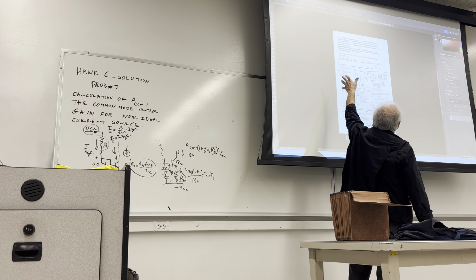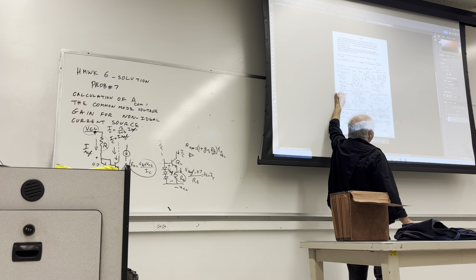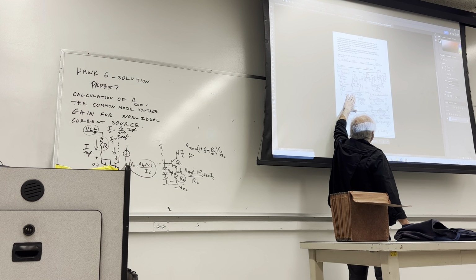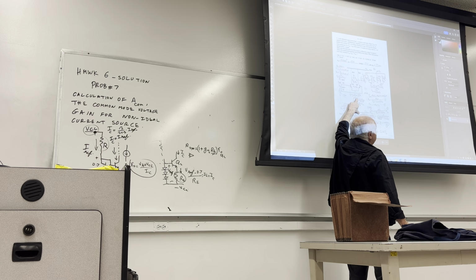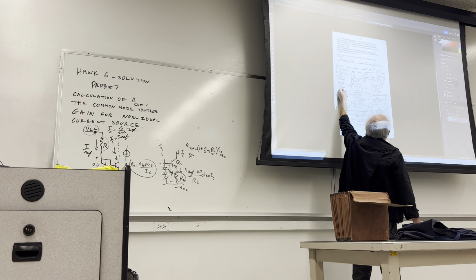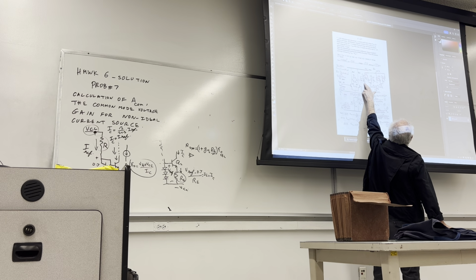We can do that, but now here, putting emphasis on how we calculate the common mode voltage gain with the existence of that constant current source, its dynamic resistance as Re, and we are putting a common voltage simultaneously to both, to this model here.